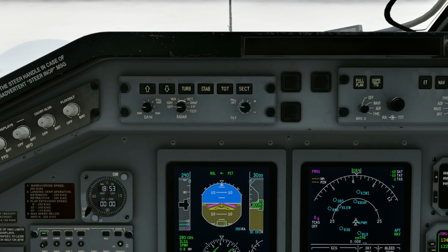Or, for example, if you're low to the ground, you might be picking up just the ground, and everything lights up like you're going to die and fly into a storm when actually you're painting the ground. So tilt is very important. The automatic mode does use the altitude, like I said, and the aircraft pitch and trajectory to figure out where it wants to aim. If you pull it out, you can have manual mode. I wish we had automatic mode on my fleet. We simply have manual, and so what we usually do is start with the radar aimed about 5 or 6 degrees up, and then bring it down as we climb, and our flight path stops being more vertical and starts becoming more horizontal.